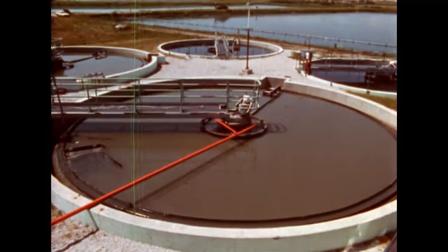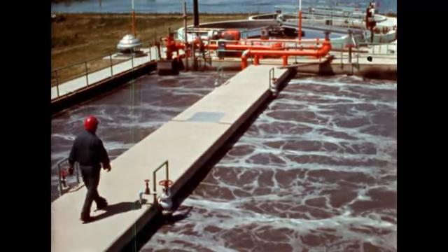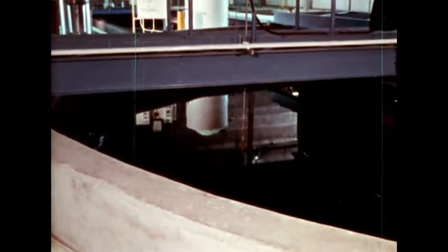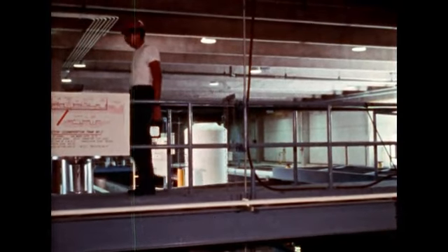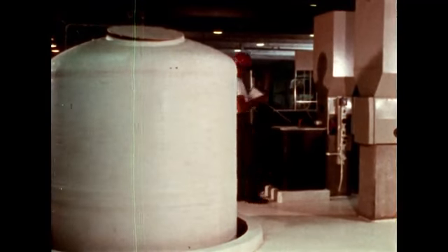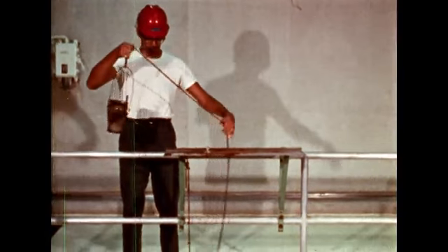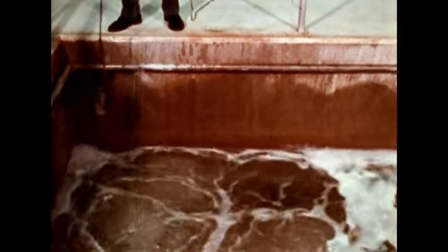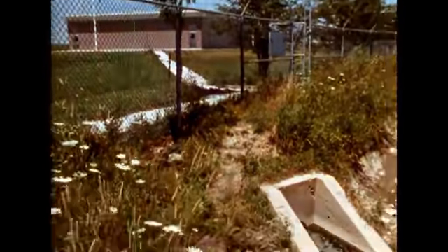But even though the treated wastewaters of Chicago, Seattle, and most other cities are piped elsewhere, they still carry high concentrations of nutrients into rivers and oceans. A third stage of sewage treatment is needed to correct this condition. In this tertiary treatment plant, solids that remain after regular secondary treatment are removed by sand filtration and microstrainers. Various means can be used to remove dissolved nutrients. Oxygen is put back in the water by bubbling air through it. The treated water, now ready for discharge from the plant, meets the standards of the Federal Water Quality Act of 1965.